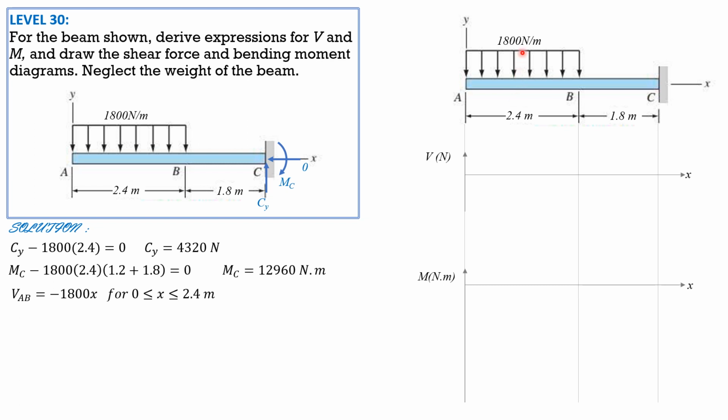Then moment AB, so plus, it is negative plus 1800 times x, moment arm x over 2. So moment AB is negative 900 x squared for 0 less than x less than 2.4. Again, negative 900 x is moment counterclockwise. We imagine this distance is x up to here. Minus 1800 times x, that's the load, which acts at the centroid of the rectangle of length x, moment arm x over 2. So that's why it becomes negative 900 x squared.